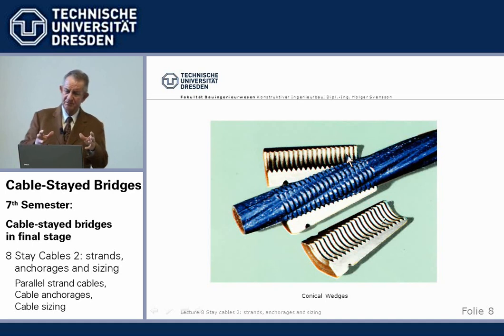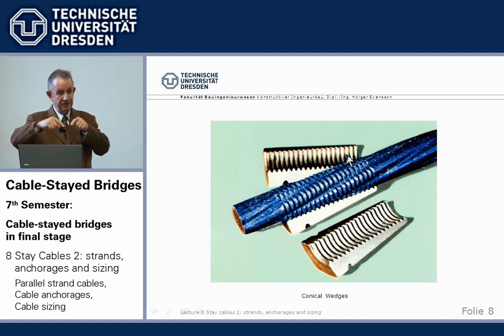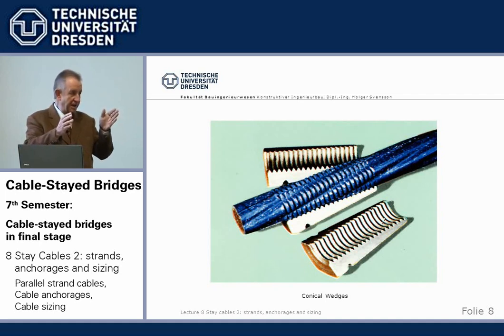if you start with a wedge with a regular tooth pattern, same teeth at the beginning and at the end, and you make a fatigue test, it breaks rather early. Why? Because most of the force goes into the first 1, 2, 3 teeth, because they bite, and there's very little force transition in the end. So the length of the wedges is not active, but everything happens in the beginning. And that sudden change of stress means little fatigue strength.